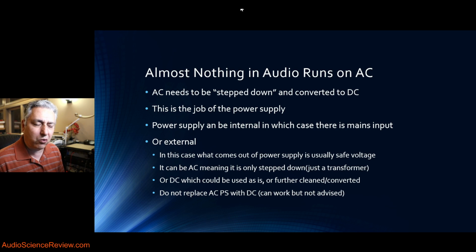Almost nothing runs on AC in audio devices. I guess if you have a turntable or something like that and it's got an AC motor, that may be one of the exceptions. But the number one thing we need to do in any audio device is take AC and convert it to DC, and that's the thing that drives electronic circuits. This is the job of a power supply, which I'm sure you're familiar with. Power supplies can be internal to a device.